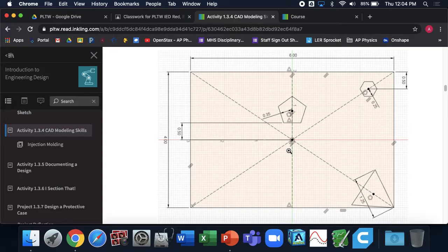Yeah, so this was the last step we just did. We needed to take the center. The other coincident constraint you're missing was the corner of a triangle coincident with the corner of a rectangle. That's what you're missing. Now you see how it turned black? That's confirmed, the size and location is defined. So you know you dimensioned it fully.